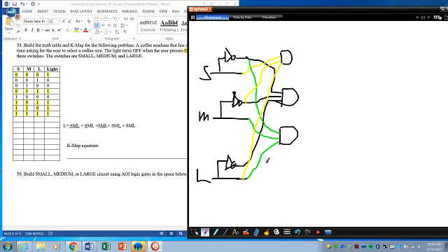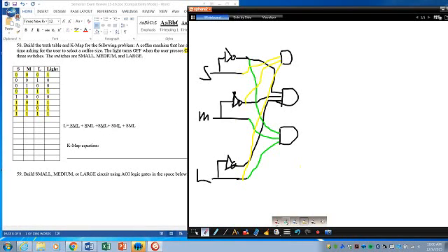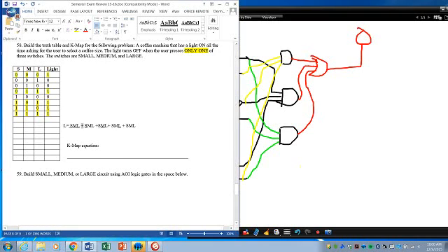I'm just going to draw 3. And then you see these 3 are connected by what? By the plus sign, right? Then you should know what kind of gate you should use. So for plus, I'm going to use an OR gate. Once again, I'm going to use a 3 input OR gate. So this should be it. I didn't draw the rest of the 2. If the equation looked like this, that's how it would look.